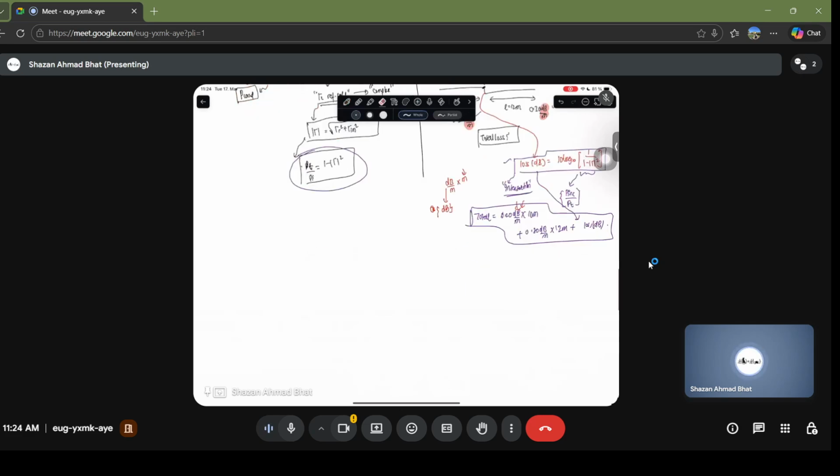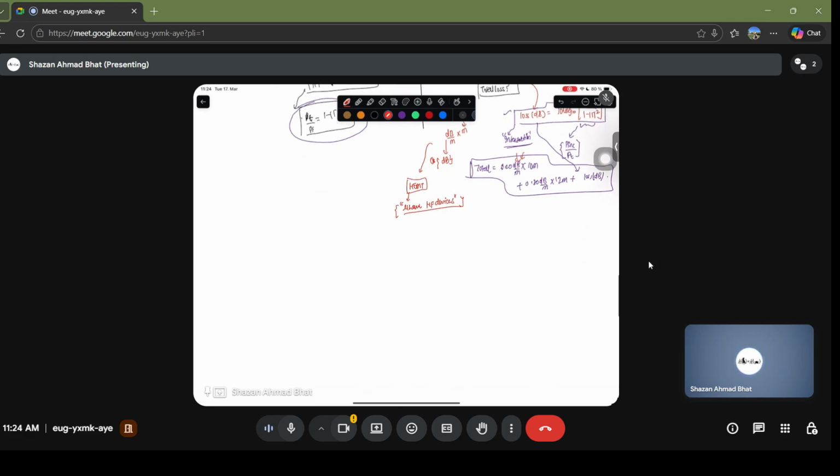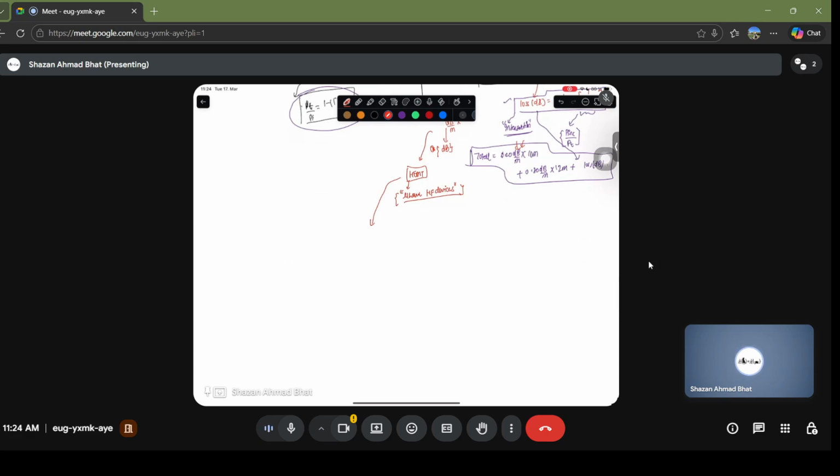And you will see these decibel per meter losses also in certain devices, like when you talk about high electron mobility transistors, which are essentially microwave, high frequency devices. These are transistors, but they have high electron mobility, so that the transit time is very small, and the frequency at which it's working is enormous. This high electron mobility transistor is made up of aluminum gallium nitride, and then there is gallium nitride,